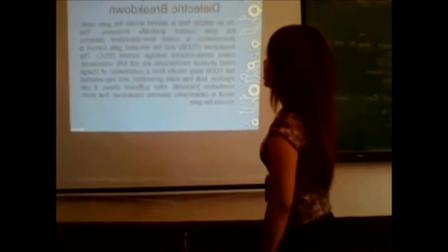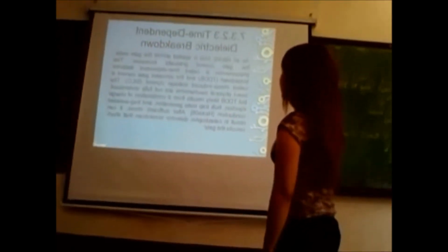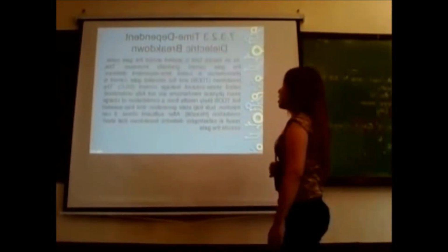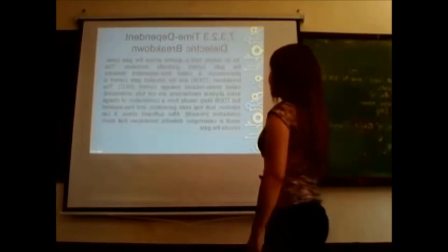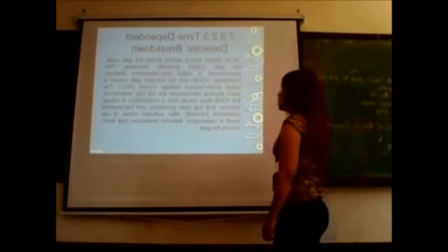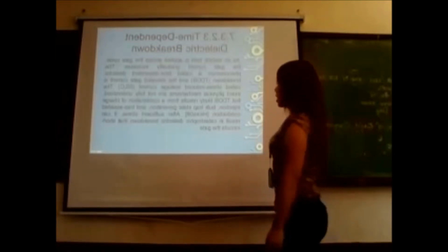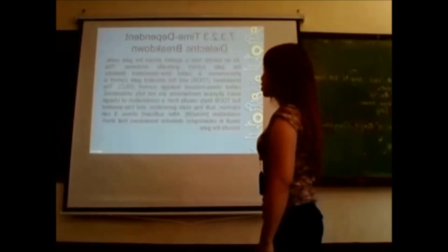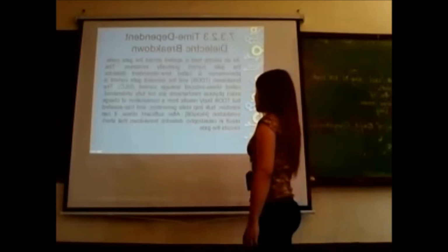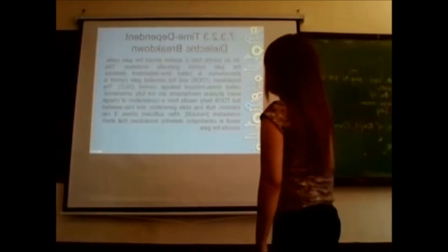Time-dependent dielectric breakdown. As an electric field is applied across the gate oxide, the gate current gradually increases. This phenomenon is called time-dependent dielectric breakdown, or TDDB, and the elevated gate current is called stress-induced leakage current, or SILC. The exact physical mechanisms are not fully understood, but TDDB likely results from a combination of charge injection, bulk trap state generation, and trap-assisted conduction. After sufficient stress, it can result in catastrophic dielectric breakdown that short-circuits the gate.